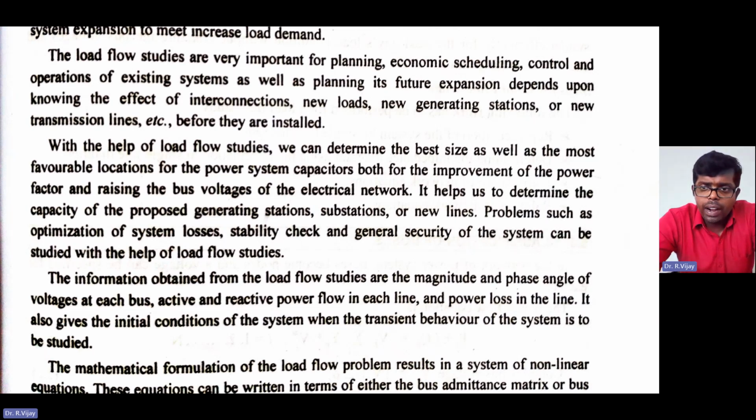But the power factor, they will see in the meters itself. Now, due to modern electronic meters, everywhere they are monitoring the power factor. If they are maintaining a power factor of less than 0.9, they will be given a penalty factor.